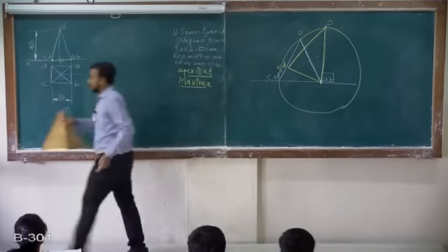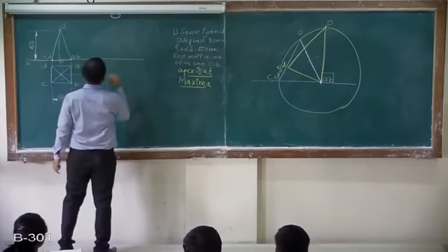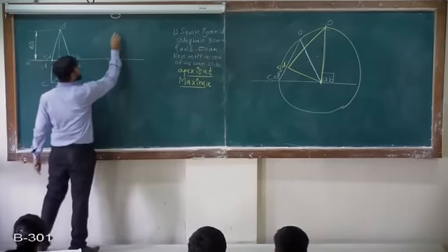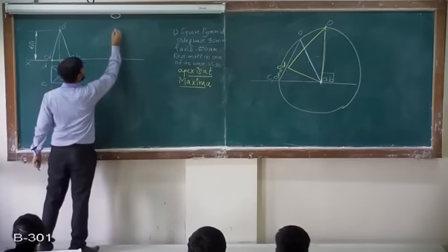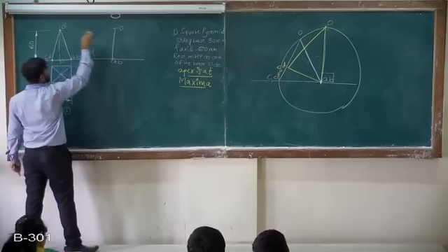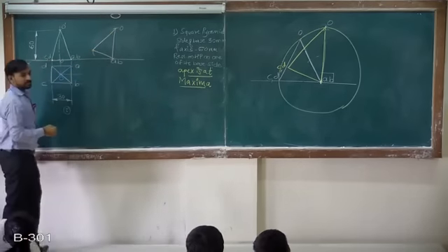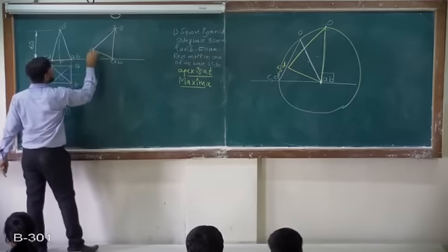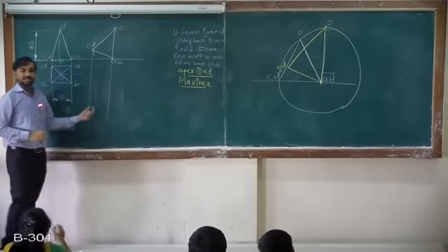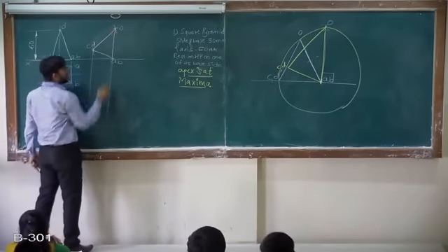Now I will draw the second stage with the same logic. Now this face ABO should be perpendicular. Take CD, mark one arc, take the AB to CDO distance, mark another arc and join it. This point will be C. Same now. The rest of the procedure is simple, and as in the previous problem, just take the projections.